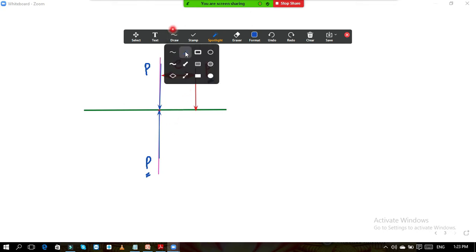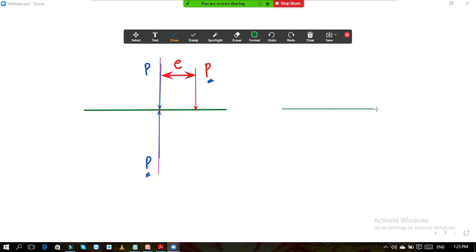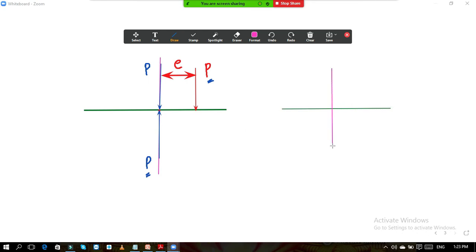Now if I show you by drawing the diagram again, this is the column surface. Then this is the center line of the column, the axis of the column, and here this is P into E. Now see, this arrow is downward, so take the tip of the arrow and rotate it towards this point. Take the tip of this arrow and rotate it towards this P, so it is in clockwise direction. So if you see, this is rotating in this direction.